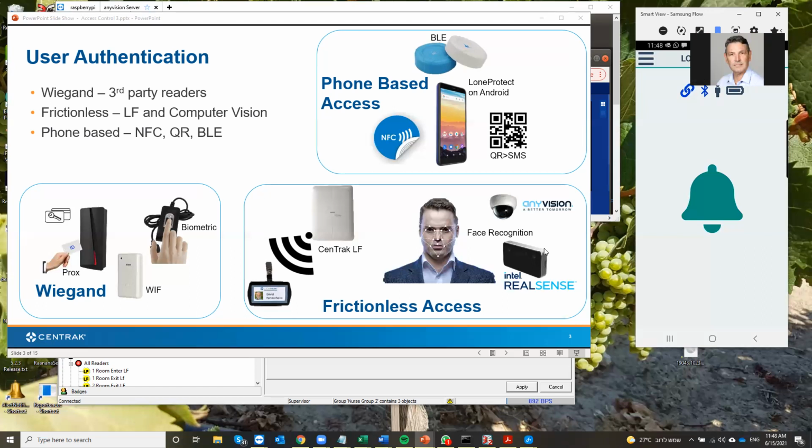So the Avigilon interface, is it a low-level contact closure or is it a high-level integration with some sort of an interface protocol from Omni? It's through an interface. I know there were cases in Israel. I don't remember the details, but I remember being involved in a stadium that we integrated with Avigilon, and we used that feature on the maps, actually. That's what I was thinking of. And so we're sending API packets to its system. It's not a dry contact. Okay, excellent. Thank you. And as Louis said, both hardwired and SDK. Yeah, just answered the question for me. Thanks, Louis.